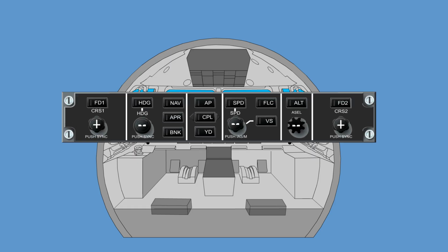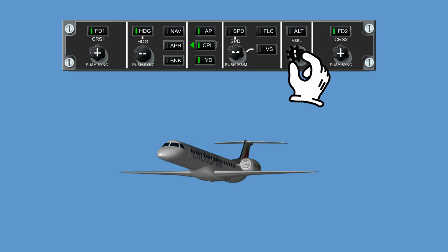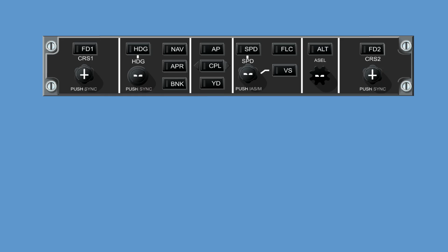The Flight Guidance Controller is responsible for controlling both the flight director and the Autopilot. The front face of the Flight Guidance Controller provides the necessary buttons and control knobs to engage the Autopilot and yaw damper, select the flight director modes, couple the Autopilot, control the course, heading, vertical speed target, indicated airspeed or Mach targets, and the altitude preselect operation.